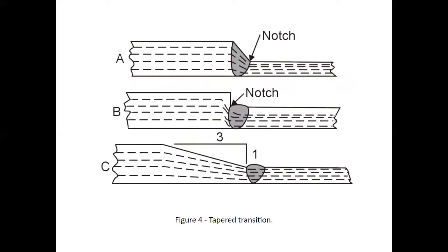A notch effect, guys, is pretty much a hard transition point where you do not get the smooth flow of stress lines. Stress lines are going to be either grouped together quite tightly, bunched or interrupted, or they will make a very sharp turn. In the welding world, it's not a good thing to have this type of effect. Often if the machine is subject to impact or vibration, you're going to see a crack develop there.